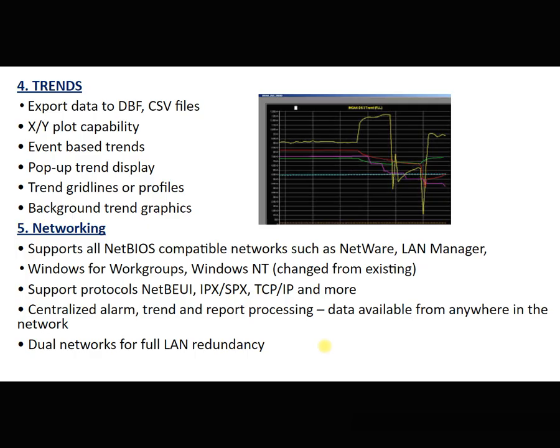Suppose the tank is filling in the field, I can get a graph like this. If it is draining, I can get a graph like this. So that is what trends are here. It's a graphical representation of the field device or a field process. Whatever trends you are getting are with respect to a particular time. Suppose now 0, you have four sensors here: 10, 12, 15, 20, like that. What's the value at 0 second, 5 second, 10 second, 20 second.